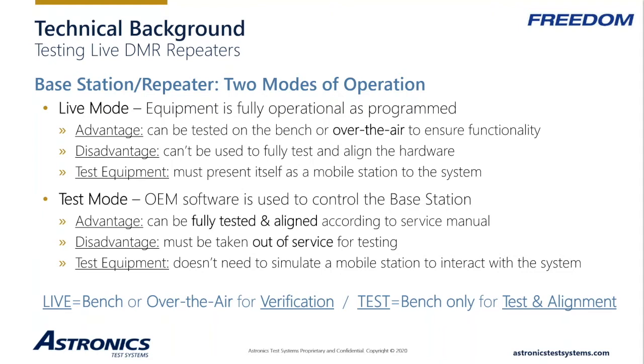Once the test equipment is connected directly to the base station, then the manufacturer's service manual procedures can be followed to fully test and align the hardware. In this mode, the test equipment does not need to send the wake-up sequence that will be required in live mode. In summary, live mode testing is for quick functional verification and can be performed while the system is on the air.